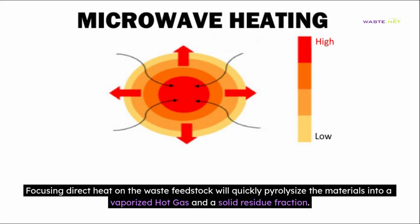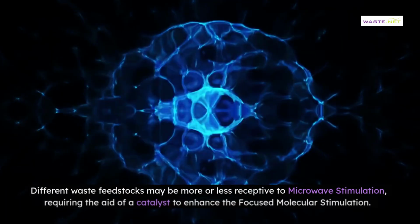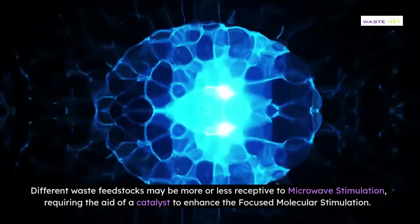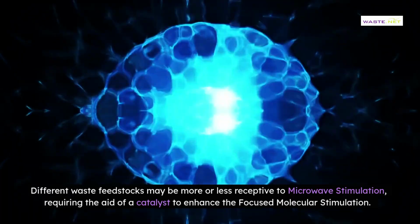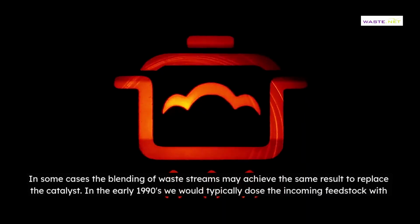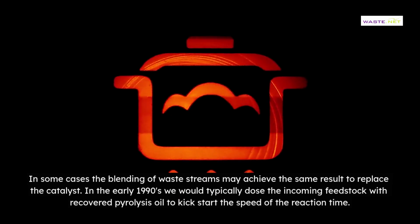Different waste feedstocks may be more or less receptive to microwave stimulation, requiring the aid of a catalyst to enhance the focused molecular stimulation. In some cases, the blending of waste streams may achieve the same result to replace the catalyst. In the early 1990s, we would typically dose the incoming feedstock with recovered pyrolysis oil to kick-start the speed of the reaction time.